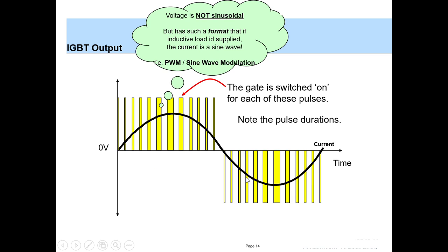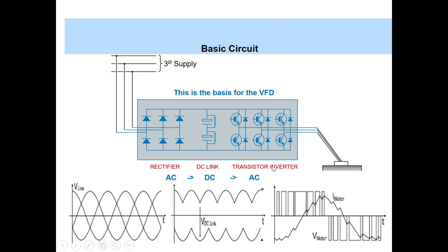Now how do we get this sinusoidal current waveform? We go back. So the motor is an inductive load, right? If you look at the current waveform here, when this pulse comes, the current gradually rises, and when we have a zero pulse, the current gradually starts decreasing, and again a pulse comes, so this current waveform starts rising again, and then it reduces here.